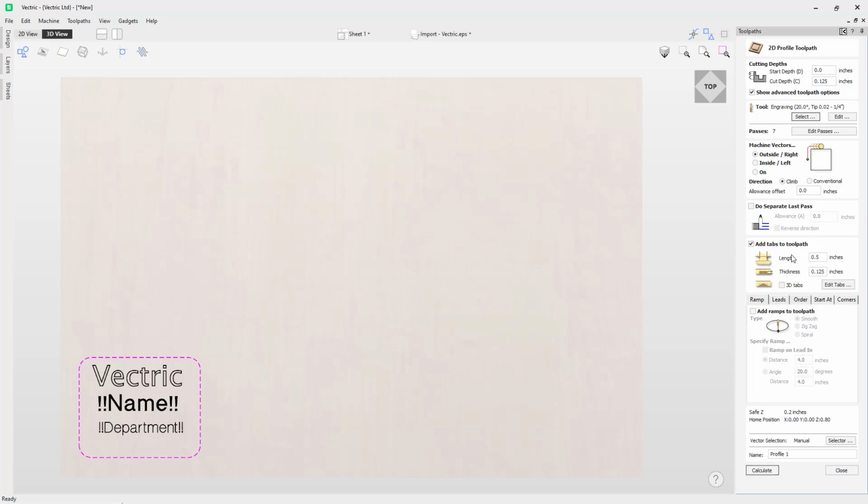Now, a couple of things I need to make a note of here. I know I want my length to be 0.1, but the thickness, I actually need a third of this. I need a third of an eighth of an inch, or a third of the thickness of my material. How do I work that out? Well, the software again can do that for you. So if you click on Z on the keyboard, if you type Z/3, so that is Z divided by 3, so that's the thickness divided by 3 equals 0.0416. So the software can work that out for you.